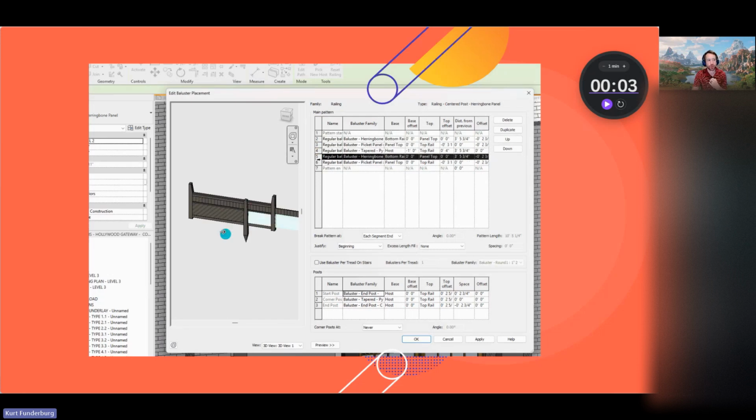And to Keaton, to your point, this is where I have a left and a right here. So I have a left chevron, like a vertical diagonal up, and then I have a diagonal down. I set those up with pre-baked fill patterns to have those lines. Then I can just change it to be like, these are this way, or if I wanted to rotate them I can send them outward and we could go that path. So again, it's allowing us to iterate really quickly without having to spend a bunch of time individually drawing railings or changing railings. Any questions?